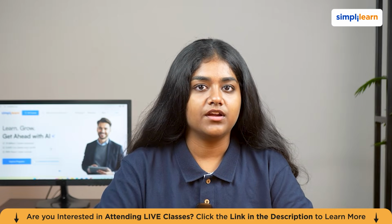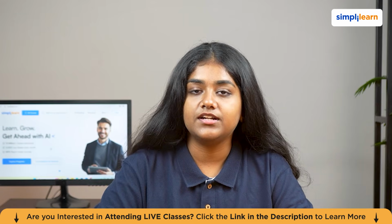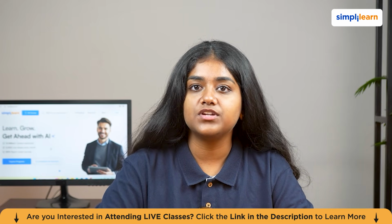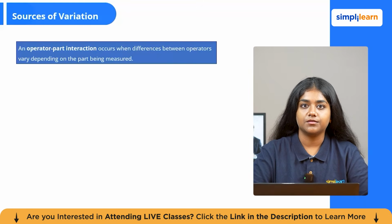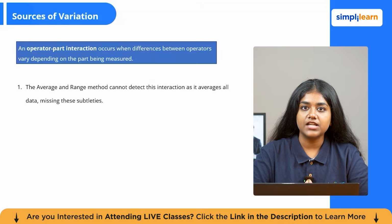So here's where ANOVA really shines over the average and range method, the ability to detect and measure interaction effects. An operator-part interaction exists when the difference between the operators is not consistent. In other words, operator A might measure some parts higher than operator B, but on the other parts, the relationship flips. So this kind of interaction can't be detected by the average and range method. It just averages everything together and you can miss this subtlety.